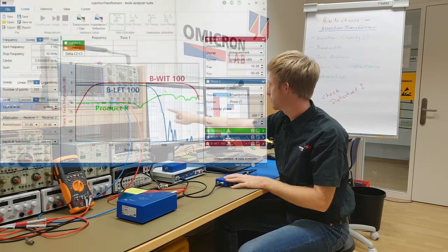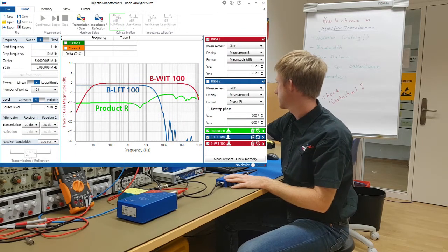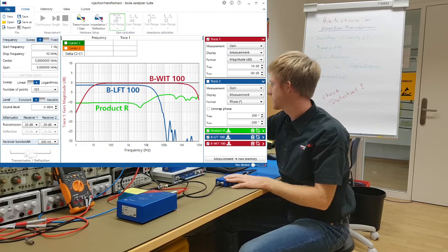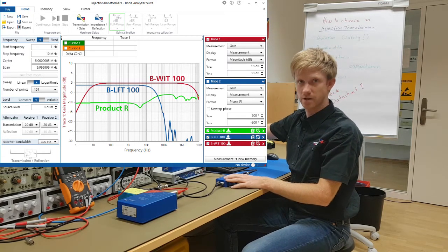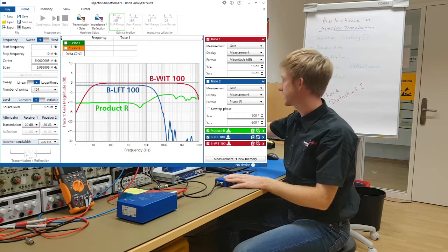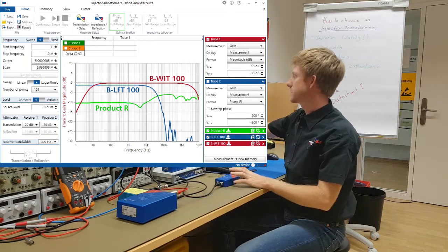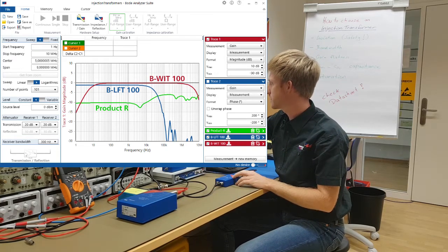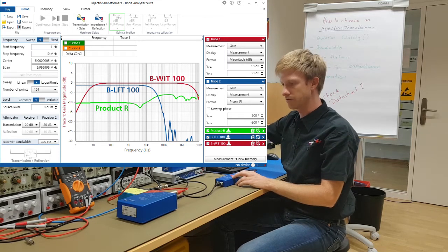It has a beautiful flat gain between roughly 10 Hz and a megahertz, and it goes up to 10 MHz. It's perfectly flat in that region, and it has nearly no insertion loss, and that's what I call the gain flatness. Then our low frequency injection transformer has nearly no attenuation at 1 Hz, so it's perfectly flat from 1 Hz to 10 kHz, and then it starts to roll off.